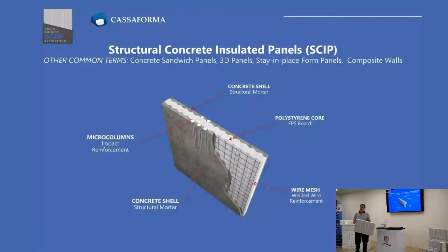And also, the way it is combined improves the acoustic insulation, because it works with another frequency, okay? Concrete has one frequency and EPS has another, okay? So they match well to get a very good acoustic insulation.